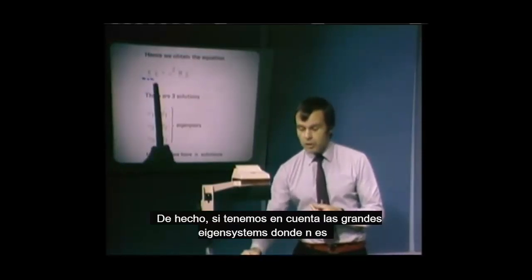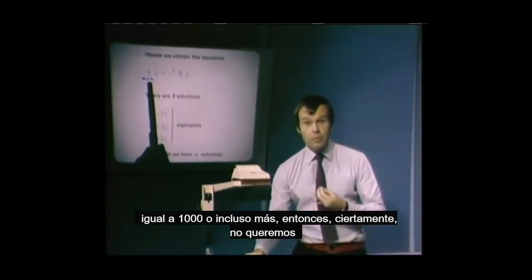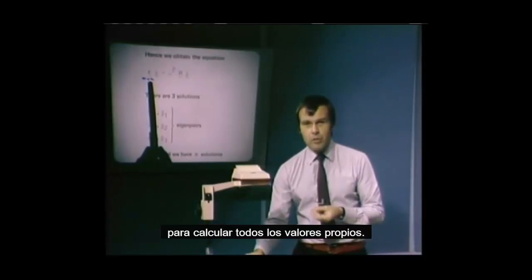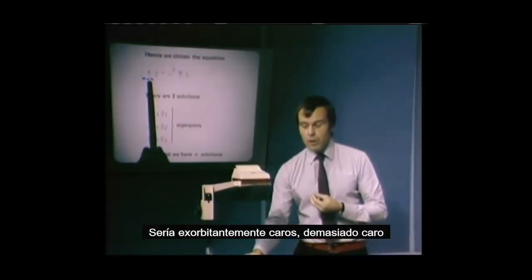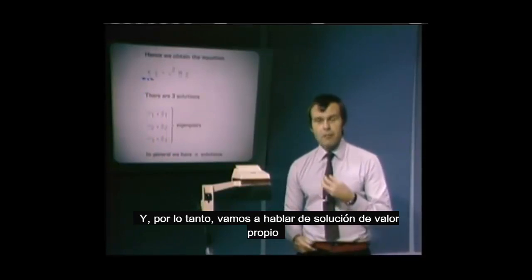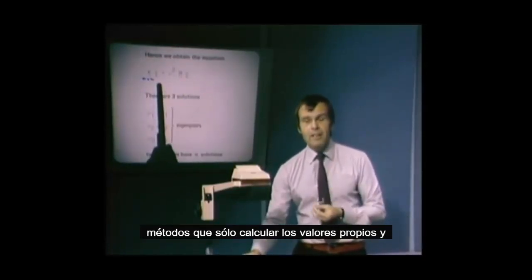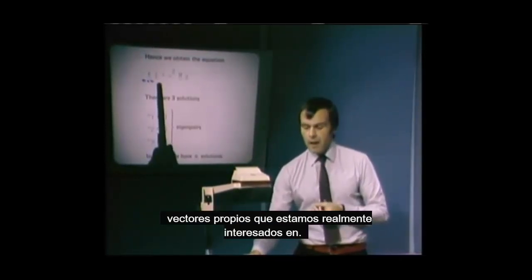In fact, when we consider large eigensystems where n is equal to 1,000 or even more, then certainly we do not want to calculate all eigenvalues. It would be exorbitantly expensive, much too expensive to calculate all of the eigenvalues and eigenvectors. We don't need to have them all in analysis, and therefore we will talk about eigenvalue solution methods that only calculate the eigenvalues and eigenvectors that we are actually interested in.